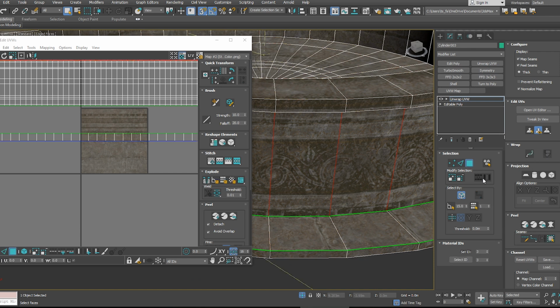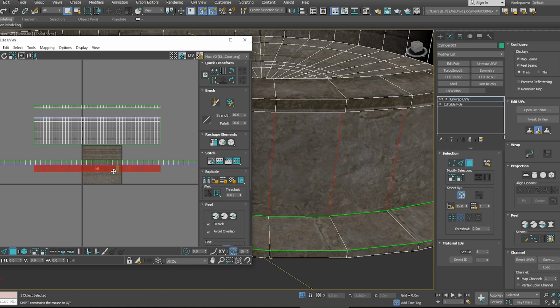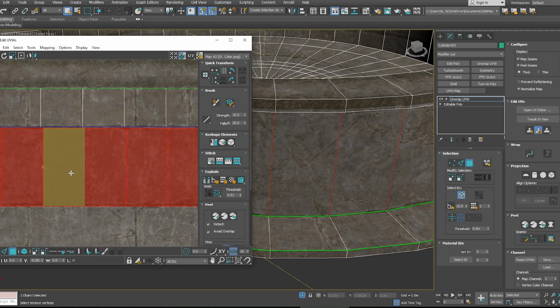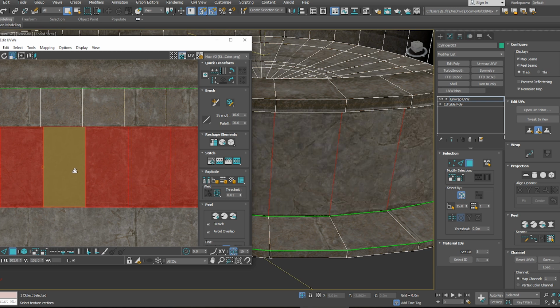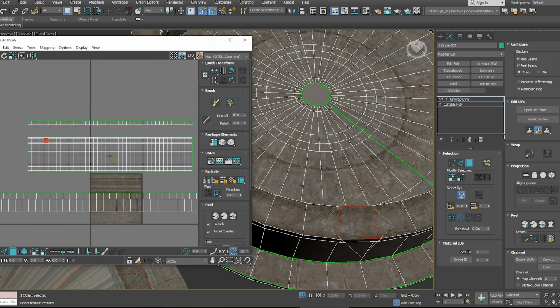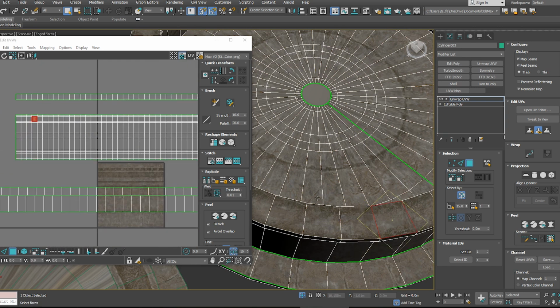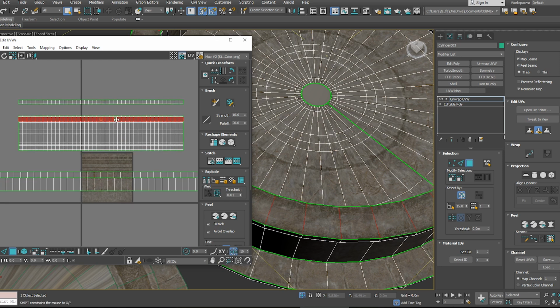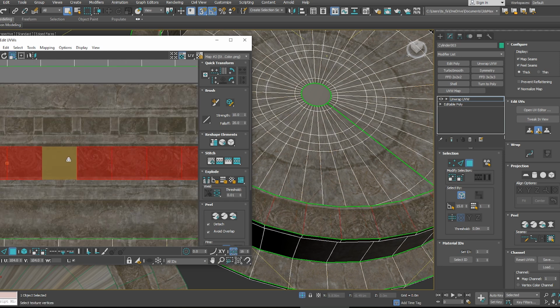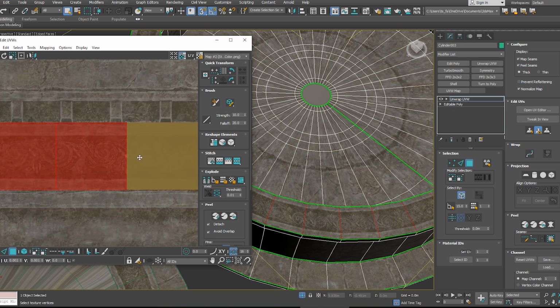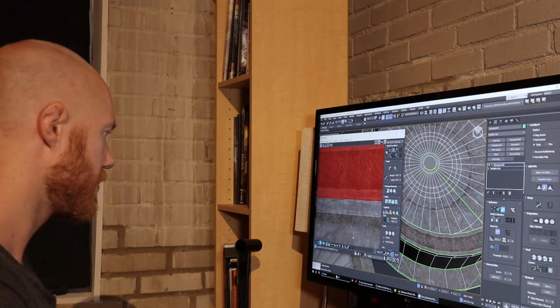And then I would just grab another ring, convert it to poly, Control B to break it, drag it down. And this one I'm going to be scaling up too anyways, just to match these edges, to give it this nice concrete with a little bit of a seam along the top and bottom. And yeah, even on your mesh, just select one of these top faces, and then quickly drag select that band, break it. Scale it up. Align those grooves on the top and bottom. Boom.